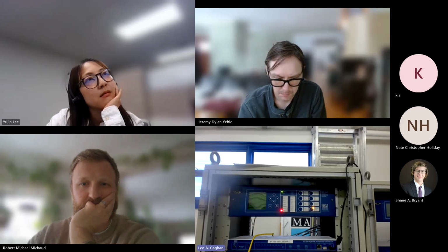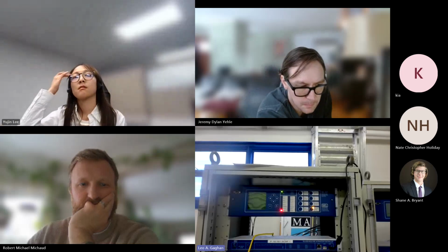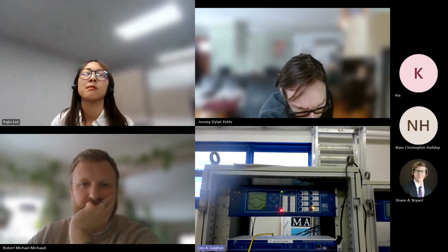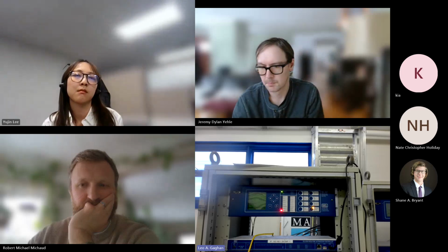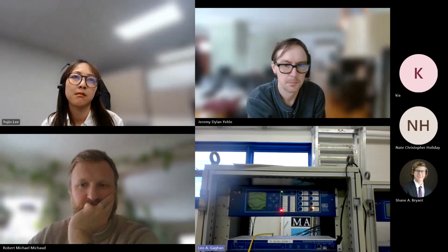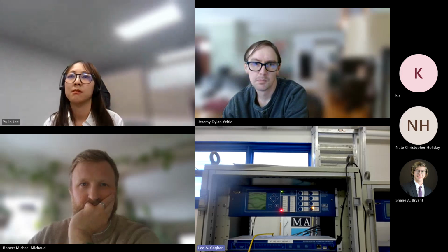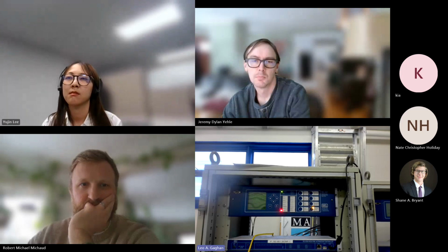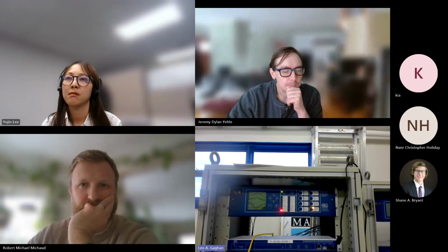So the next one is a pretty common function. It's called breaker hold. And the goal of a breaker hold is you've got people on site and we don't want to be opening and closing this breaker for safety reasons. So with breaker hold, you can't open or close the breaker. Right? We want to keep these people safe. It's kind of built into some places into a switching and tagging scheme.